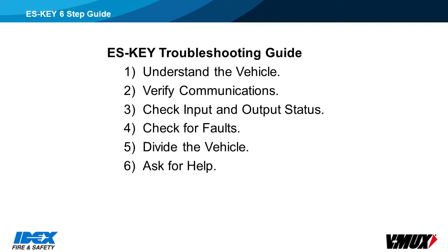Step 1. Understand the vehicle. Step 2. Verify communications. Step 3. Check input and output status. Step 4. Check for faults. Step 5. Divide the vehicle. Step 6. Ask for help.